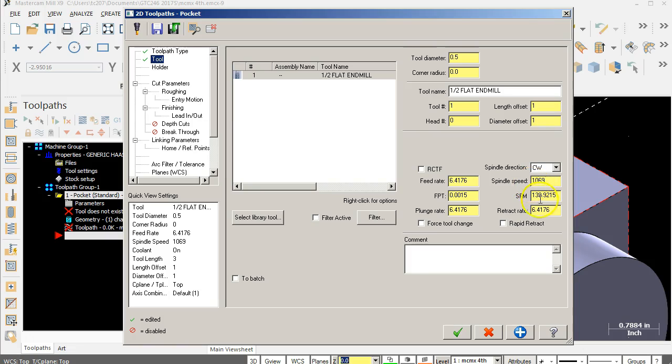And the more of these parts that we run, the more of these that we do, and we go from close to the table to further extensions, then we're going to be able to make some of these determinations. What is better? Do I go a little less RPM, a little less feed rate to avoid some of that vibration and chatter, or is it okay and we just go with our normal speeds and feeds? So let's start off with a mid-range for the 1/2 inch carbide.